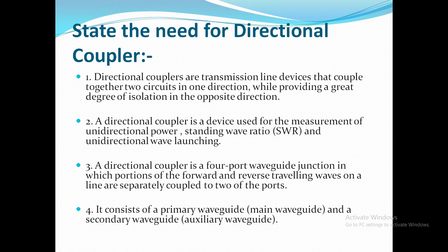The microwave signals traveling through a waveguide need to be analyzed in terms of the input power, coupling factor, directivity, etc. The coupling factor is a measure of the ratio of power levels in the primary and secondary lines of the waveguide. Hence, if the coupling factor is known, the power at the input of the waveguide can be determined.